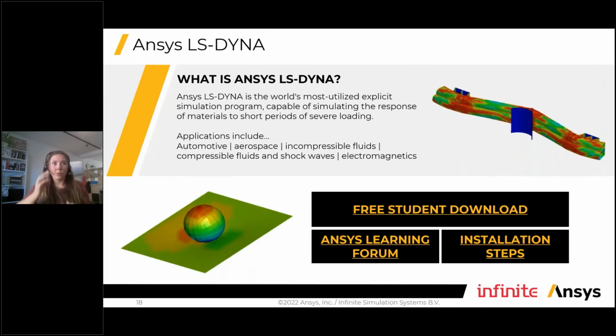Then a very specific one, it's Ansys LS-DYNA. LS-DYNA is the specific tool for crash testing. This is mentioned separately because it works a little bit differently than maybe an Ansys Mechanical or an Ansys CFD. Again, here, a lot of links where you'll find more information. But if you are interested in doing crash testing, either impact testing or drop testing, Ansys LS-DYNA is the one that you should test out.